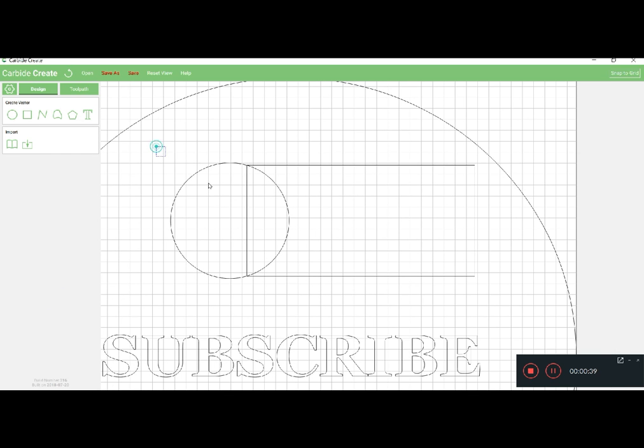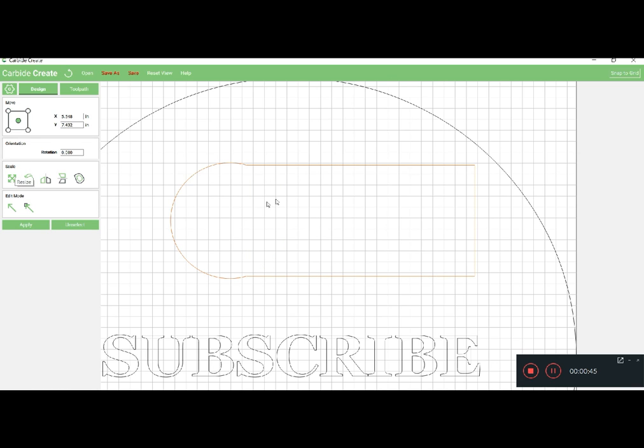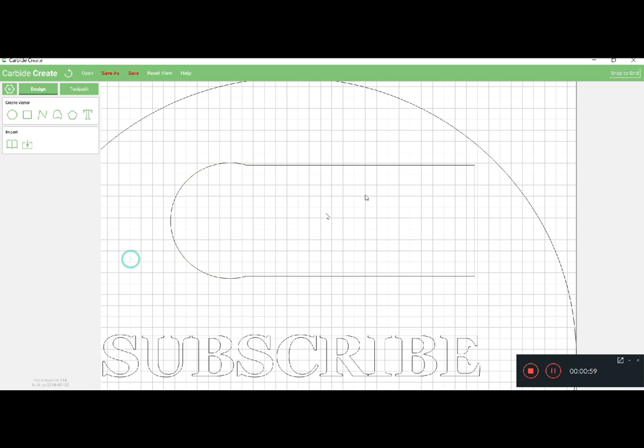We're going to take these and we're going to grab them. You can see here, if I click this, we turn two objects into one, right? I could still maybe bring this down a little bit smaller, but now you're only going to have one toolpath, whereas you would have two separate toolpaths. So that's pretty cool. If I were to hit apply, great. If I wanted to get out of there, if I made a mistake, I could hit Control Z, and that would bring me right back to where I needed to be.